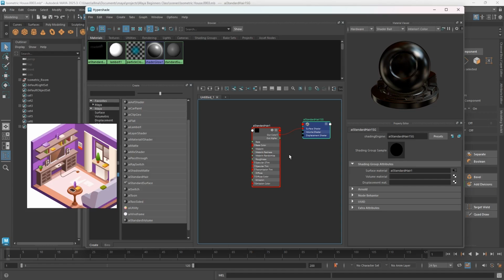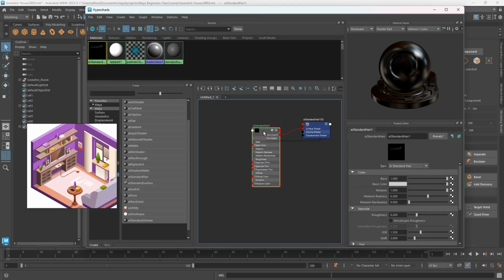You have to import all those textures here from your Hypershade, one after the other, or you have other options to do that. But if you want to do that directly from the Hypershade, you're going to make use of the aiStandardSurface, depending on the renderer you're going to be making use of. If you're going to be making use of Arnold, you definitely go into export from Substance Painter as an Arnold AI Standard, and that is what you're going to export as.